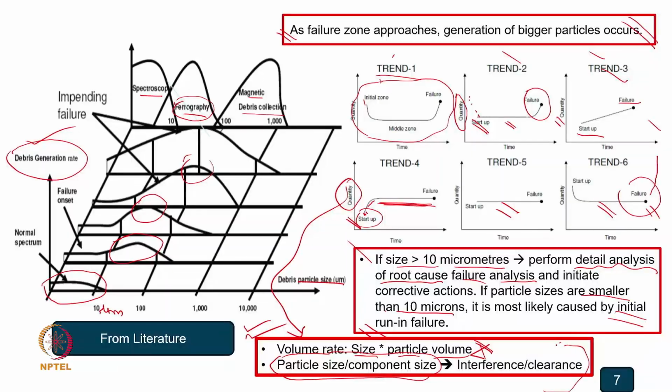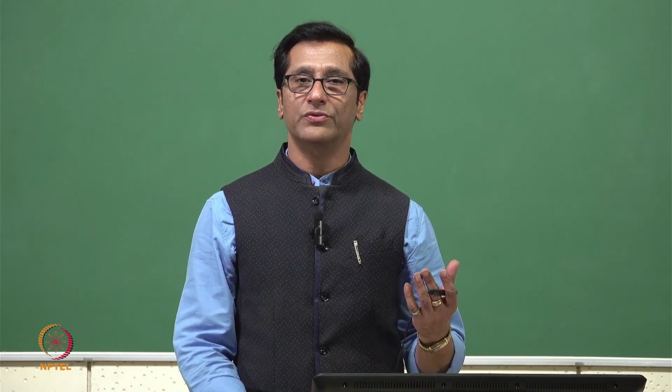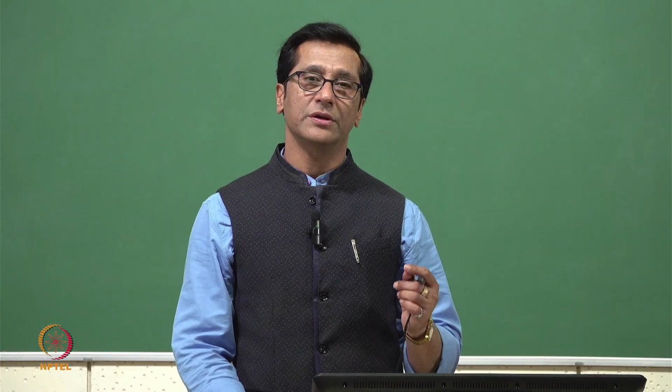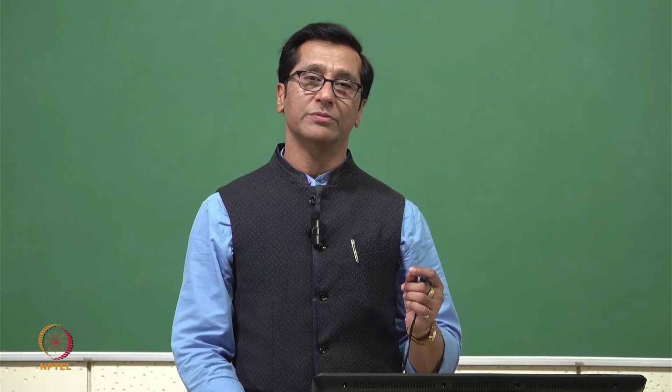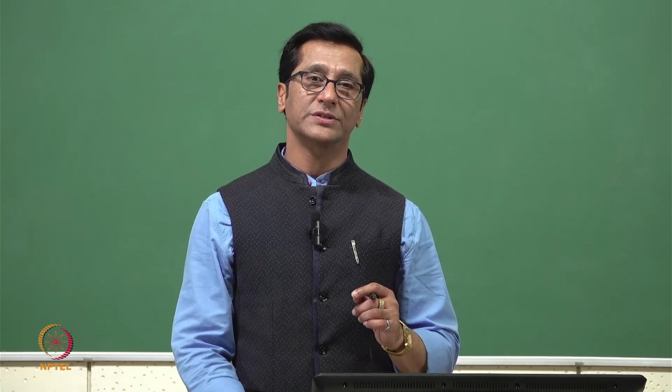A special case comes with fretting wear, where there is an interference fit or transition fit, and we find that even in a nut and bolt connection, they don't show any wear from outside, but because of micron level vibration, particles get loosened from a surface, and those particles start pitting the surface itself.